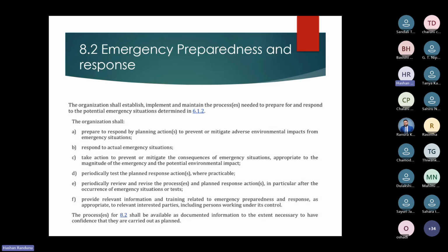If you use sandbags, then you should have easy access to those sandbags, right? If you use gates to close those drainages, then you should install gates at the drainages, right? Even that is not enough. So you have identified controls, then you have infrastructure for that, right? Then if there is a fire, who will close those gates or who will put those sandbags into drainages? So then we need to assign responsibilities to a particular task, right?